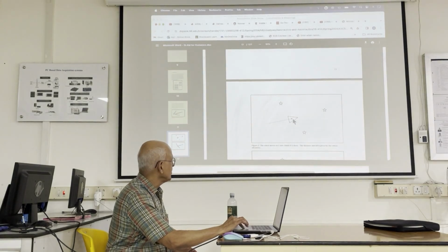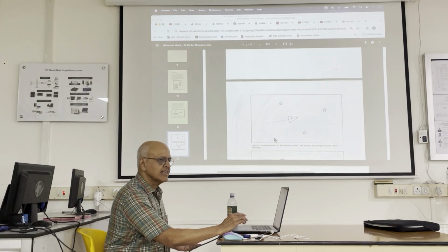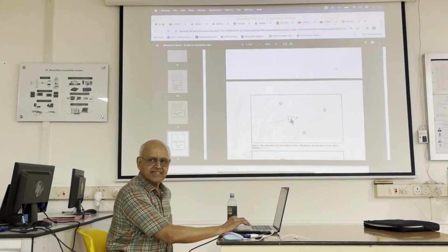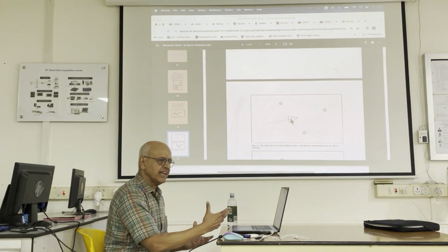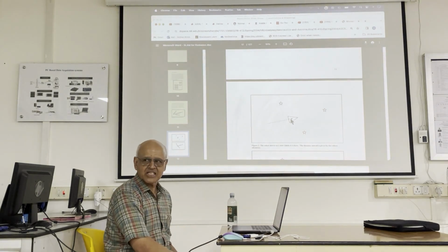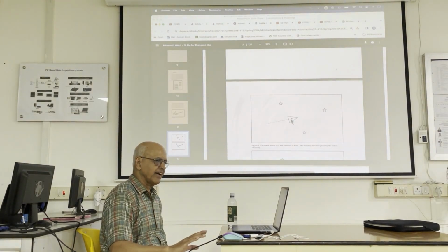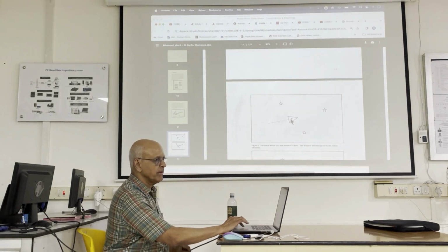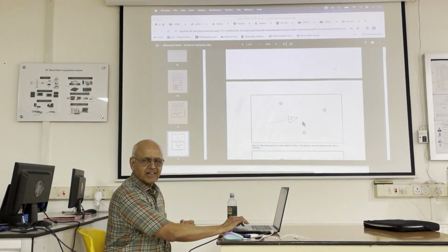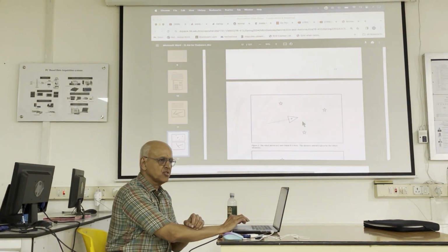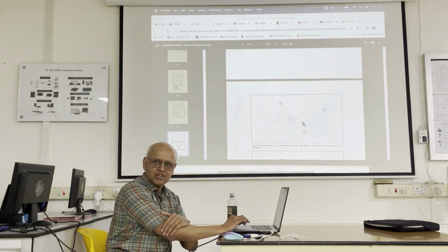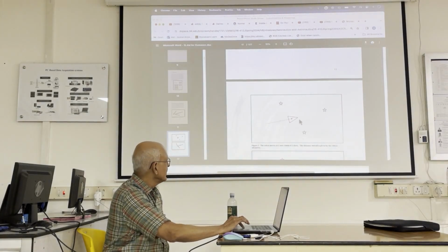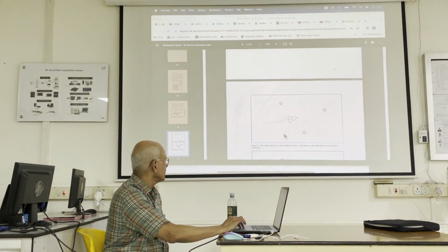So how do you measure where the robot is now? The robot moves, and it now thinks it is here, and that's through odometry. So that's not the exact position of the robot, right? It's odometry telling you the robot is there. And you know odometry has some error. So odometry will fail eventually, but we're not going to let it fail, because the position is going to be corrected. Based on what? We're not using GPS. SLAM typically does not use GPS. SLAM is meant for indoors. It can be used outdoors also, but typically it's used indoors. So we're going to use SLAM here to correct the odometry.